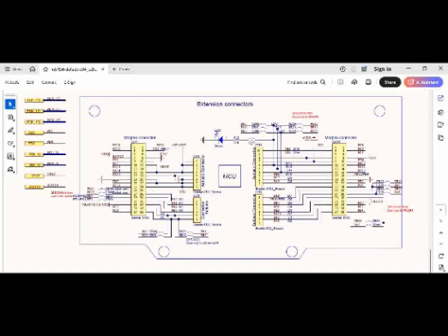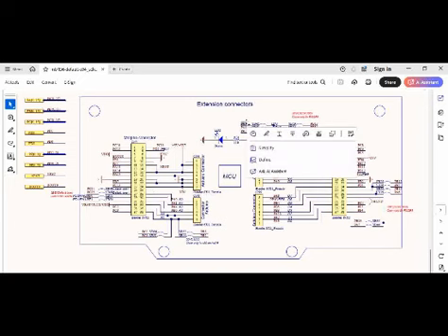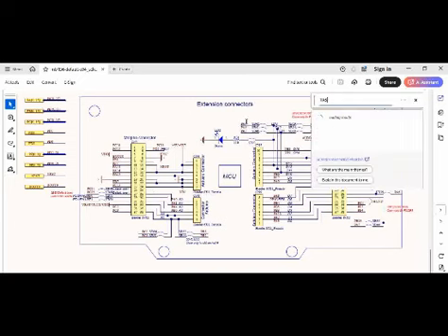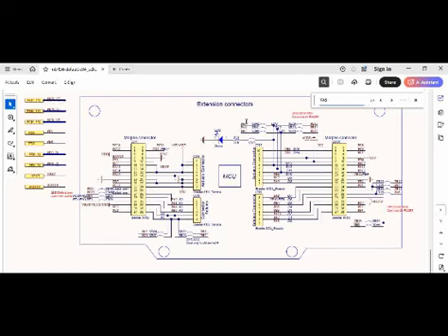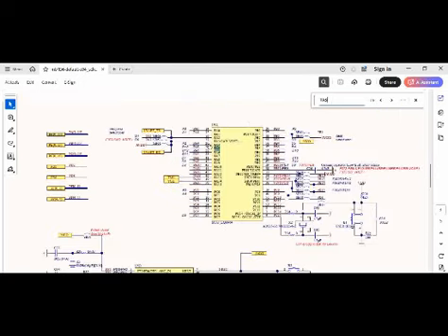Okay, ensure that SB21 and SB42 on your board are mounted so that PA5, if you actually search for PA5, okay, these are all searchable schematics. PA5, you see here, it's going to the bus, and you can see here it is mentioned as PA5. Again, it is connected through the bus to the respective pin through the node name.